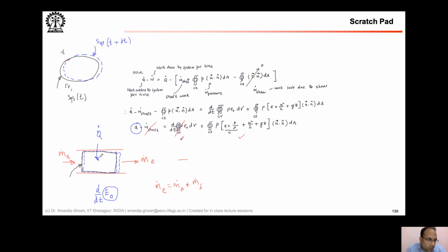A lot of things are going on here, but what I'm saying is, if you're not throttling, or not having dynamic phenomena, if you have a steady burn in the combustor, not a combustion instability kind of situation, or flame blowout, or flame flashback, then in most of the flight envelope condition we have a steady state behavior. So we say, let this be 0 for the steady state assumption. Keep in mind, this is an assumption. If it is not a steady state, you cannot assume that.